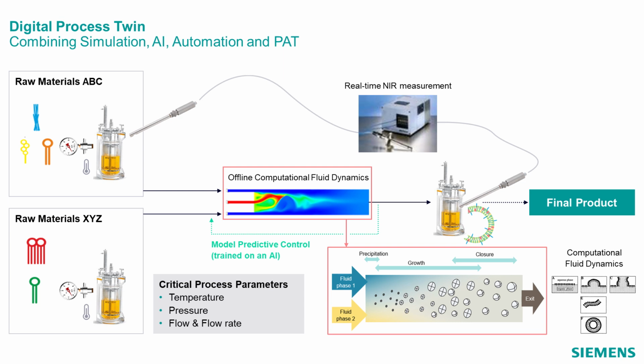As this is a continuous process now, we are also monitoring the quality in real time by integrating an NIR measurement tool via SciPath. And the third thing that Siemens has achieved here is to combine these real-time measurements of SciPath with an MPC control unit so that we have an even better control over the complete process by model predictive control applications. On top of that, machine learning technology is even helping to continuously improve the prediction quality of those MPC units.